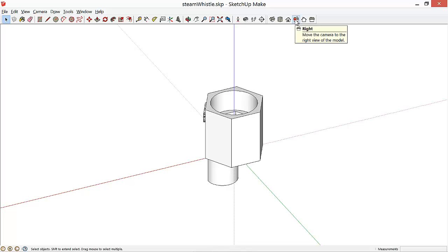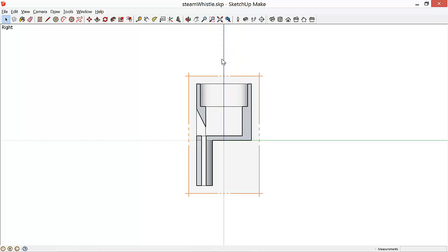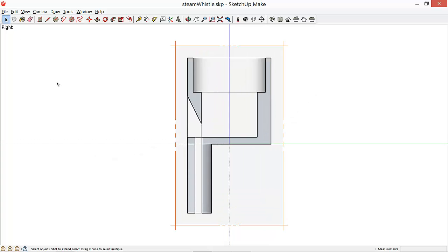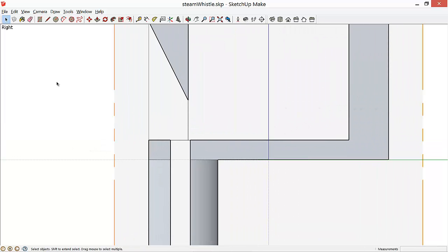Okay, now let's look at what's going on inside with the blade in more detail. We'll select the side view and then section plane, and rather than placing it directly on a face, we'll look normal to the plane that we're looking in, and here we can really see pretty well what's going on inside the whistle. We'll zoom in, and in particular, look how the blade lets a thin sheet of air pass underneath it. Let's see how big that gap is using the Dimension tool.